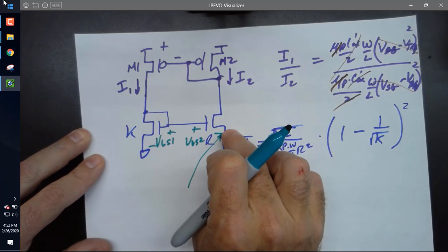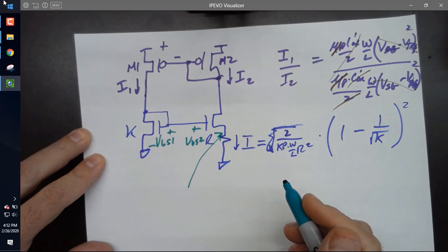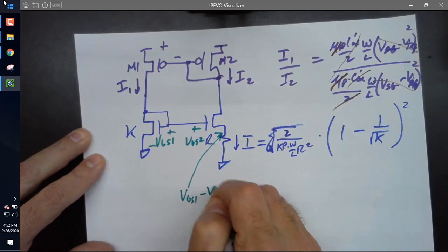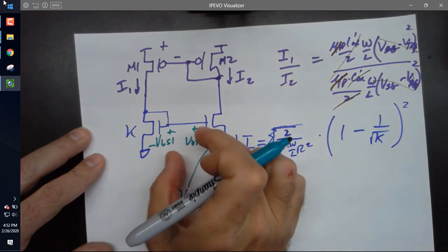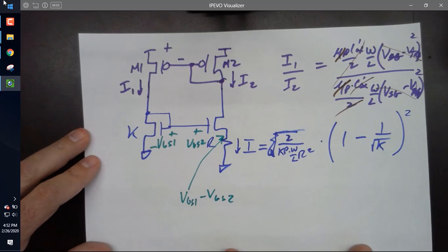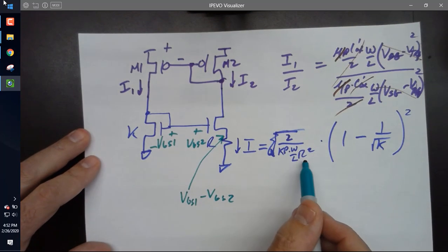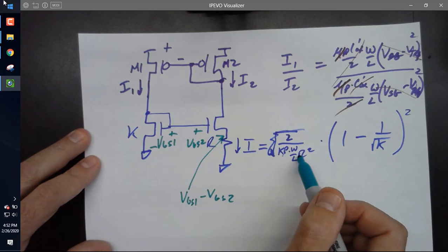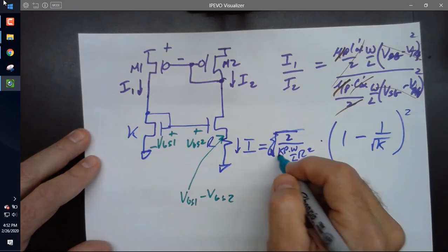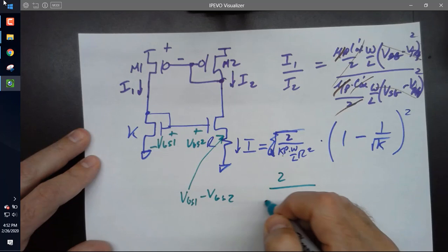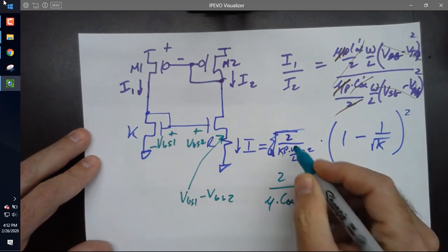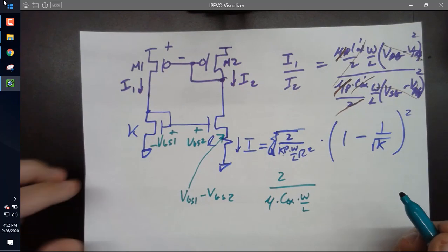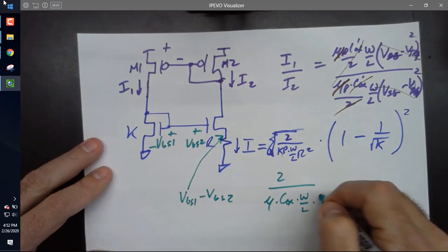All right, so this voltage is what? And if I put in the equation for the threshold voltage, what happens? Divide out. So then your answer is, oh, threshold voltage doesn't come into play. So what comes into play here? Mobility and resistance. So if I look at this, I've got 2 over mu times Cox times W over L. Does W and L change with temperature? No. This is R squared.